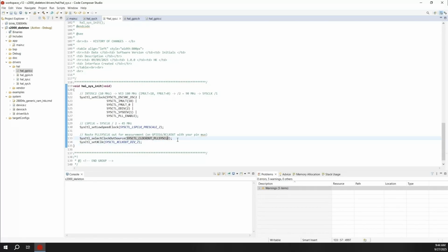Maybe for the beginning, we can just put internal oscillator 2 on our pin, as shown here. On the F280049C LaunchPad, we can use GPIO 16 for this purpose. All we need to do here is configure that pin as the special function output for X clock out. Since we haven't yet talked about the general GPIO configuration, I will just show you the minimal code needed without going into details. In the next lesson, we will cover GPIOs more systematically.